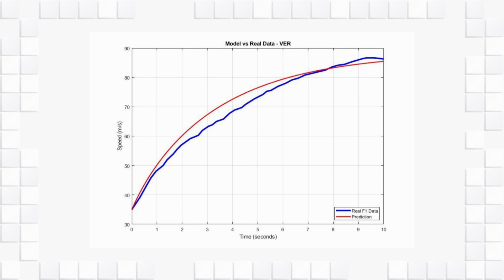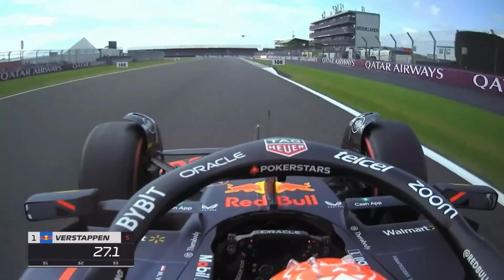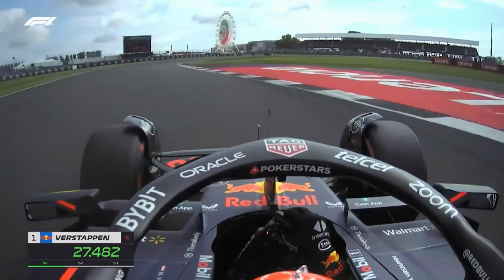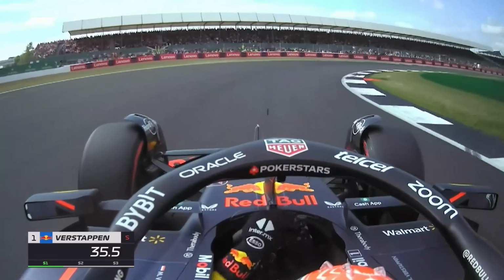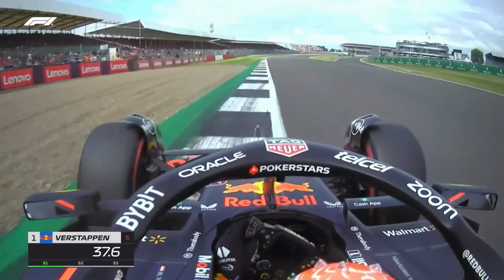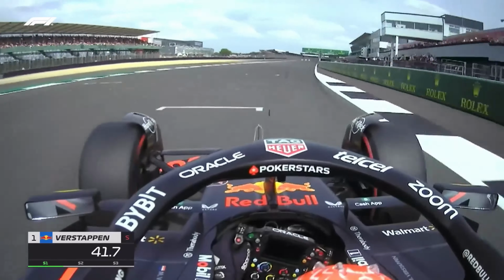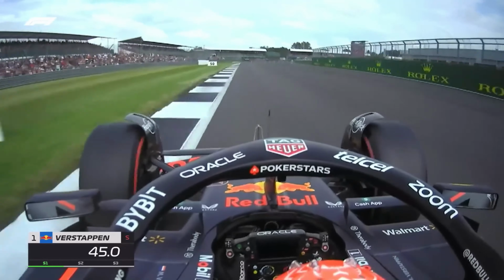My project models how an F1 car accelerates from low speed to high speed while working against drag, which increases with the square of velocity, and rolling resistance. Using Newton's second law, I converted the net force on the car into a differential equation describing velocity as a function of time. I then solved this equation numerically with the ODE45 tool to generate a complete acceleration profile.